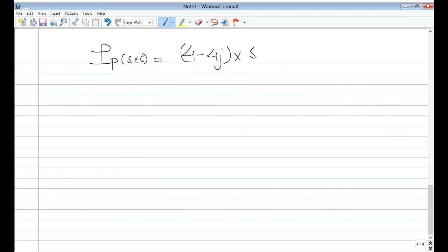Secondary turns are 50. Primary turns are 100. That is 2 minus 2J. So that will be the reference of the secondary current into the primary winding. Now it is saying it is drawing a magnetizing current of 1 ampere. The value of capacitance to be connected in tertiary to improve the power factor to unity.